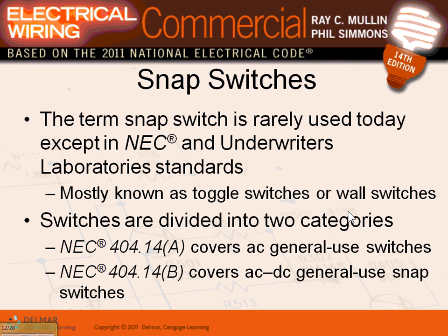What's the mechanical difference between? I don't know the way this. Here's what I know. If you are to break a DC circuit, the amount of arc is higher and more severe than an AC circuit. So you need the contacts to be more robust.